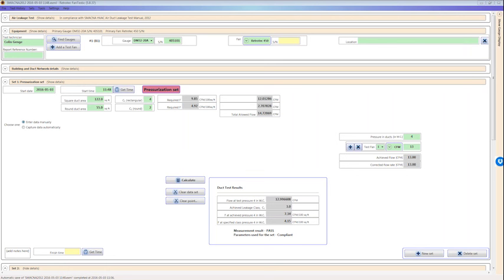So if you're working with an installer that's not used to things being tested, you do want to make sure you give them some guidance as to how much. Usually it's several hundred feet of a linear main path that is tested. And if you're going to test a variety of incredibly long or vertical sections or all of the branches, you're both going to be in trouble. You're going to find that you have to take things apart versus preparing them ahead of time into manageable, testable chunks.